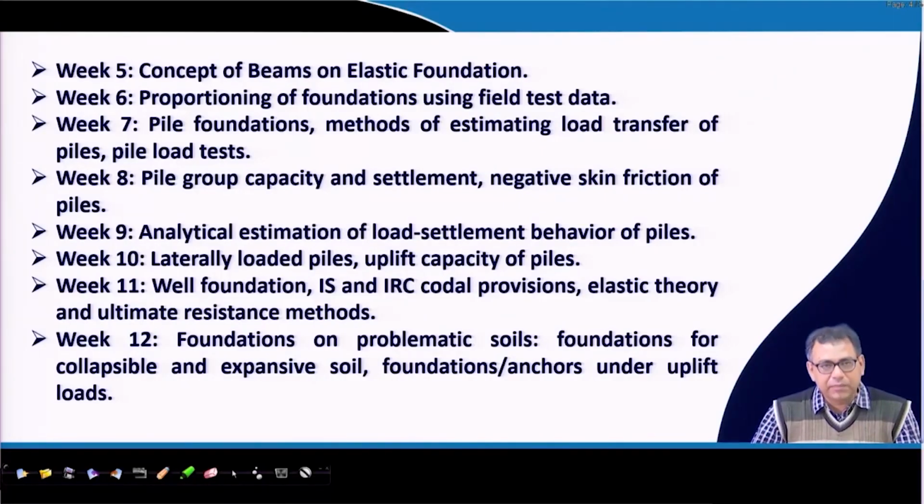Then I will discuss the pile foundation, stress transfer or load transfer mechanism along the pile, then pile load test, then pile group capacity and settlement calculation, negative skin friction. Then I will discuss the analytical estimation of load settlement behavior of piles, then laterally loaded piles, uplift capacity of the piles, and I will discuss the well foundation and different codal provisions.